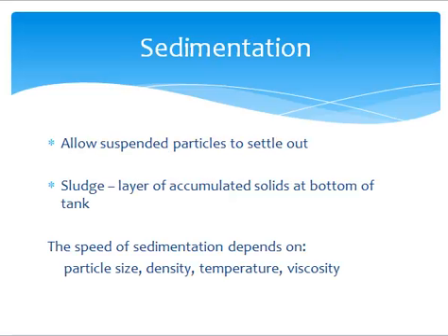Let's now turn our focus to methods of water purification. We will begin with sedimentation. This is the process by which suspended particles are allowed to settle out. The accumulation at the bottom of the tank is called sludge. The time of this process will vary depending on particle size, density, temperature of the water, and water viscosity.